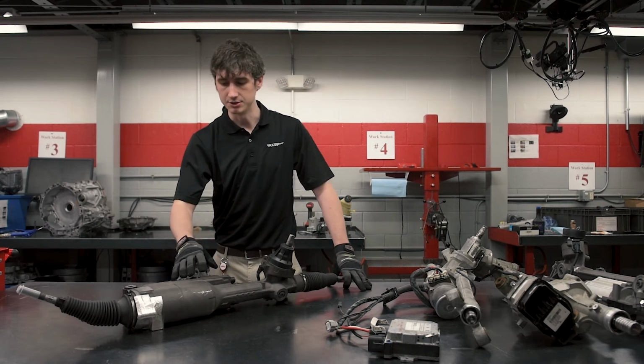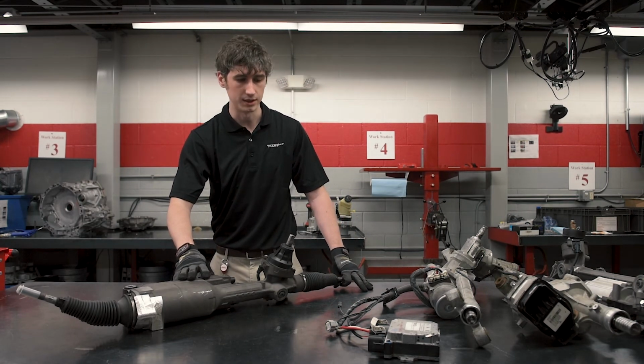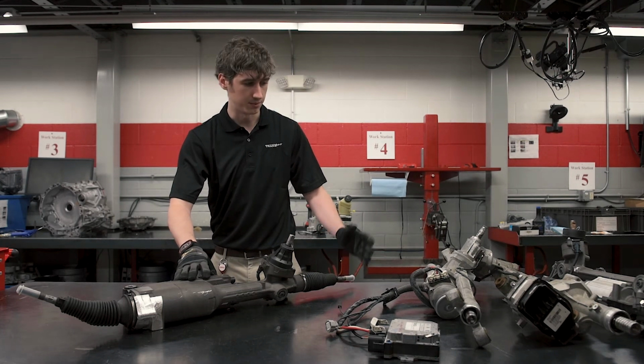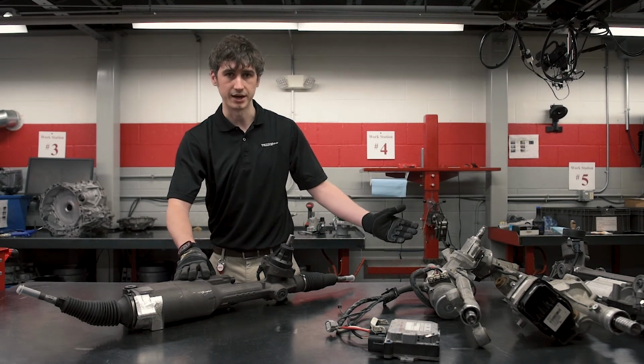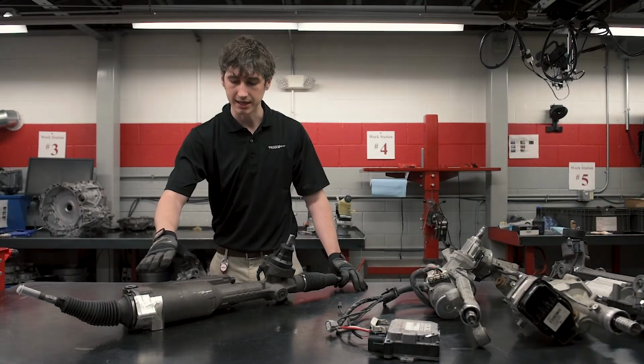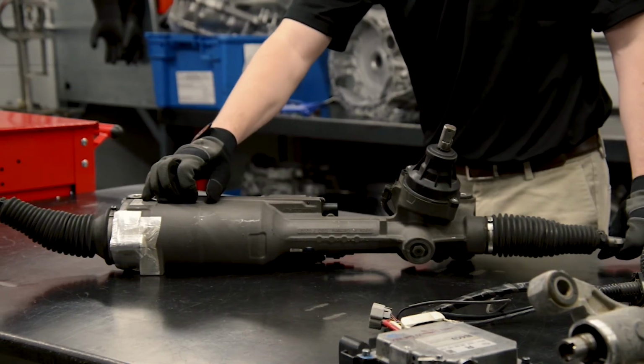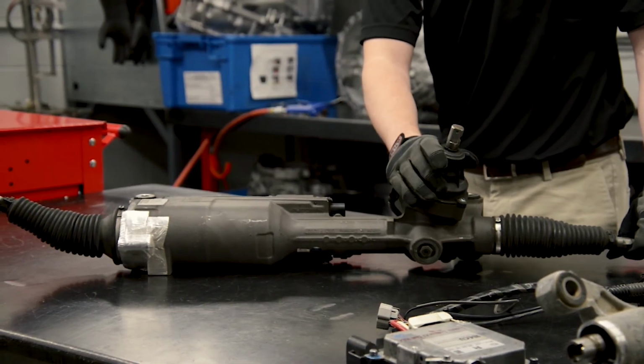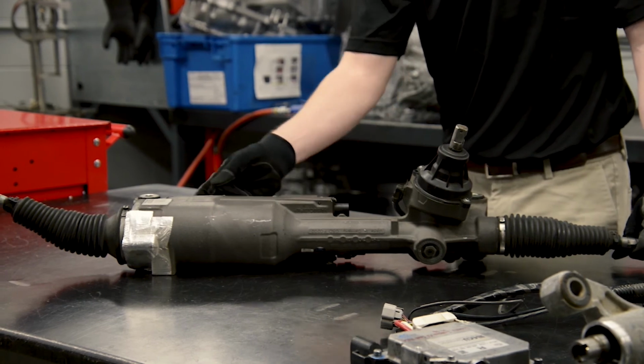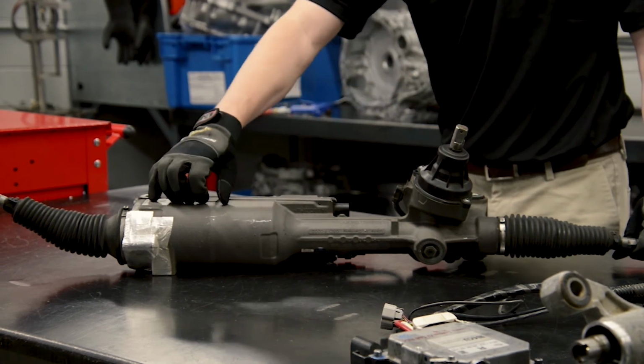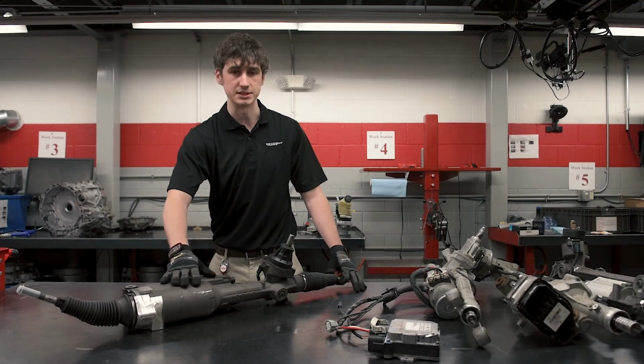Finally, this is going to be a direct driven rack. So instead of having it by a pinion drive or by a belt or by a worm gear, this is actually going to have the motor around the rack bar itself. So you're still going to have the torque sensor on the pinion. It's going to drive the electronic portion and drive the motor, but the motor is actually going to be right around the rack bar. And that's what's going to give you assistance.